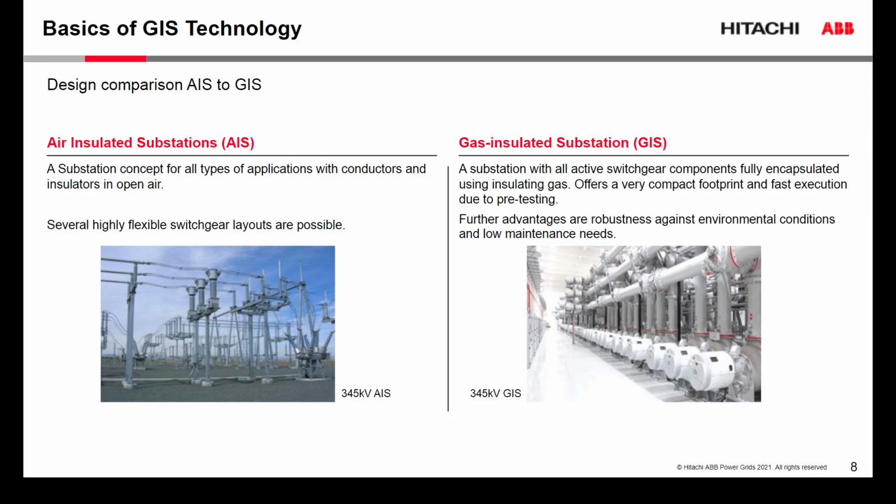On the left picture, we see that the conductors are high up in the air, supported by insulators to ensure the necessary safety clearance and clearance between the conductors is in place. For 345 kV, for example, the safety clearance is 15 feet.